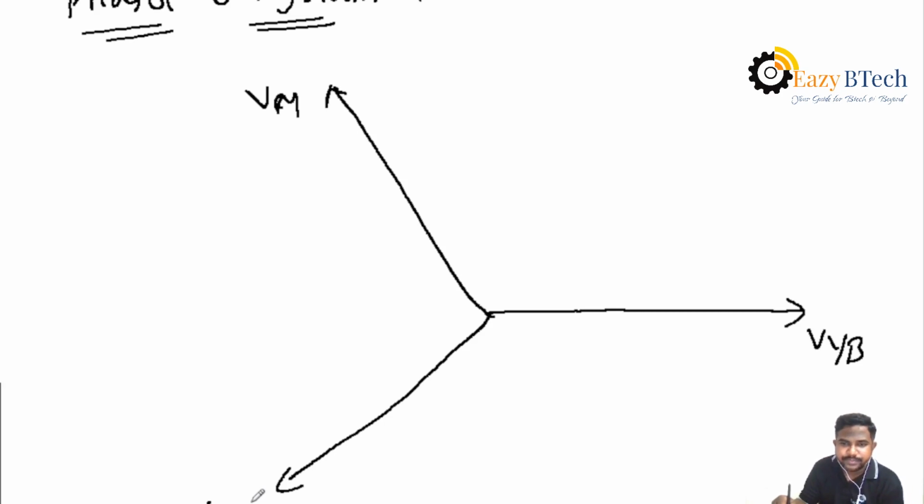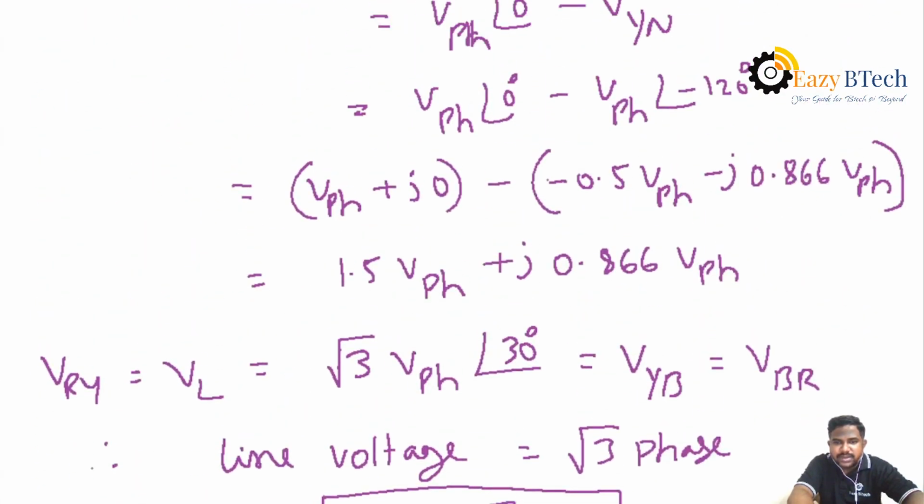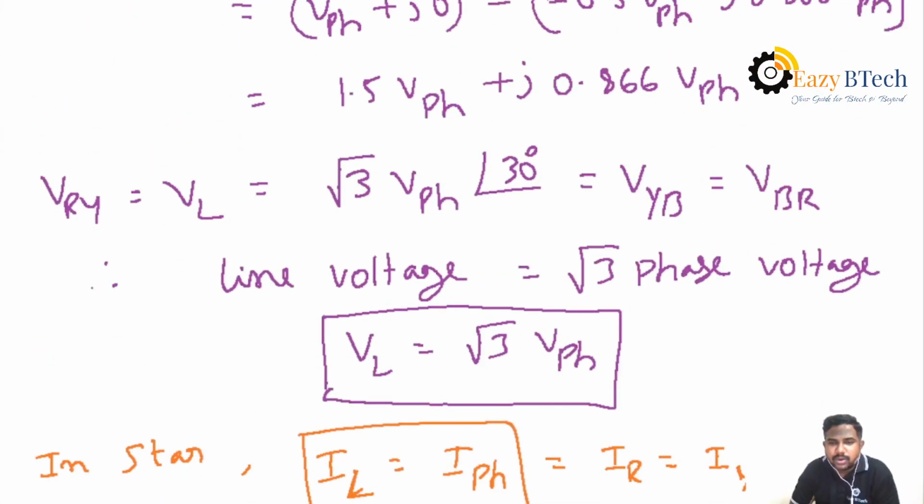We know that. Then according to the phase relations, VL equal to root 3 VPH. What is the meaning here? That is the current, and also the current relation is IL equal to IPH. If the current has phase angle phi, what is the phase angle of the voltage? 30.